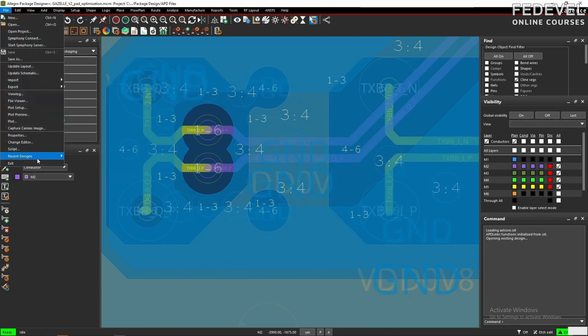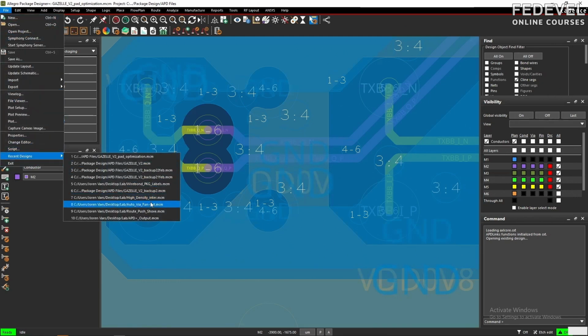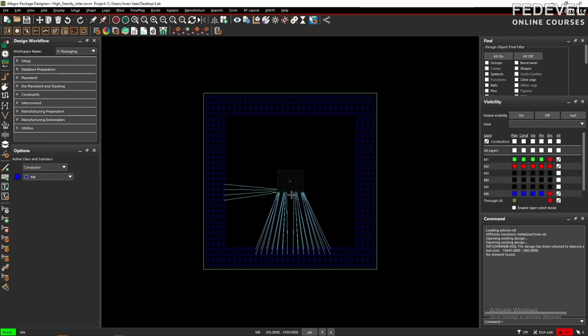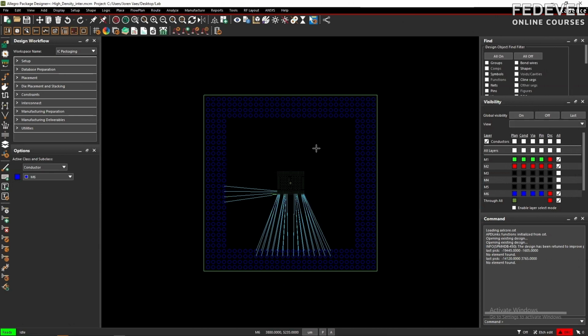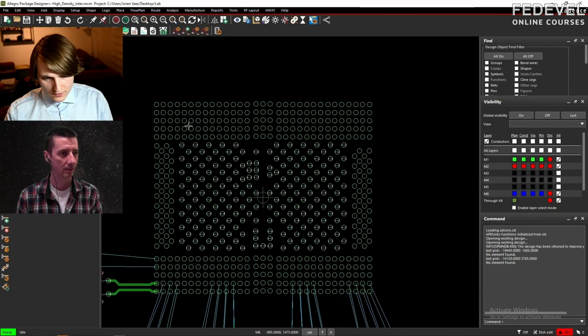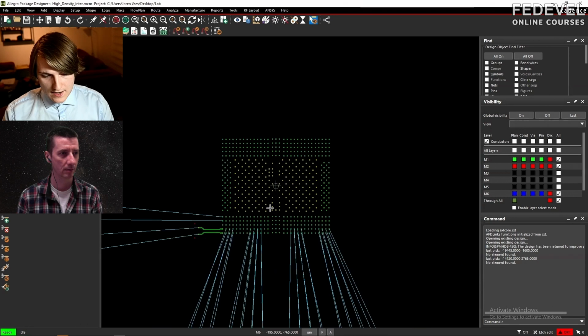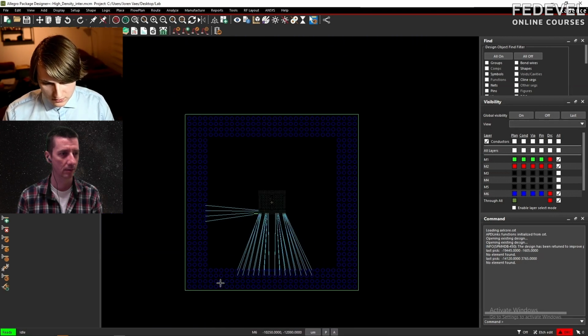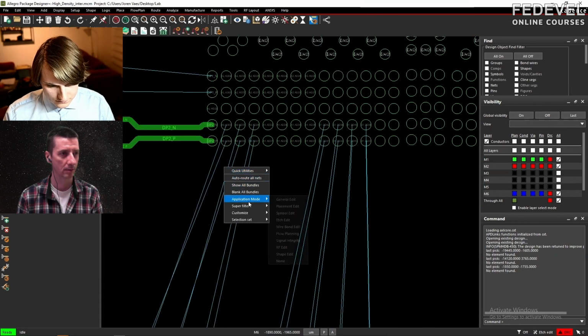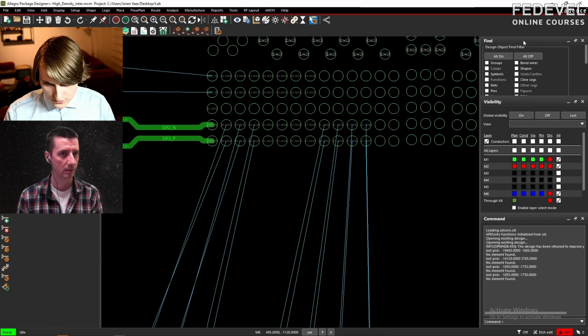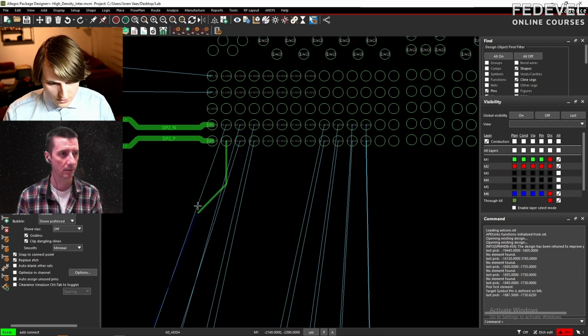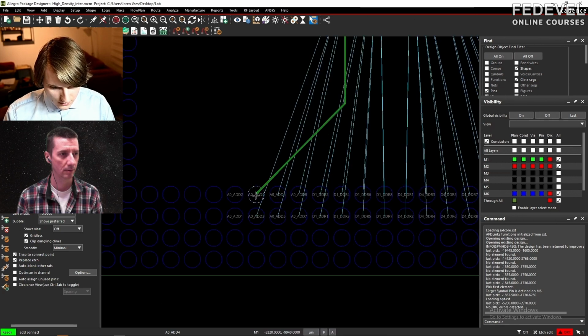Yes. So for example, we have here the package design. This here in the center would be a file you export from the chip design tool. And these are all of the different bond pads, or in this case, they use copper pillar bumps, solder balls, and you then import it just like with PCB design, and you connect it to the BGA balls on the outside. You do your routing just like you would in any other tool. So I just route it, connect it here, voila, add some vias.